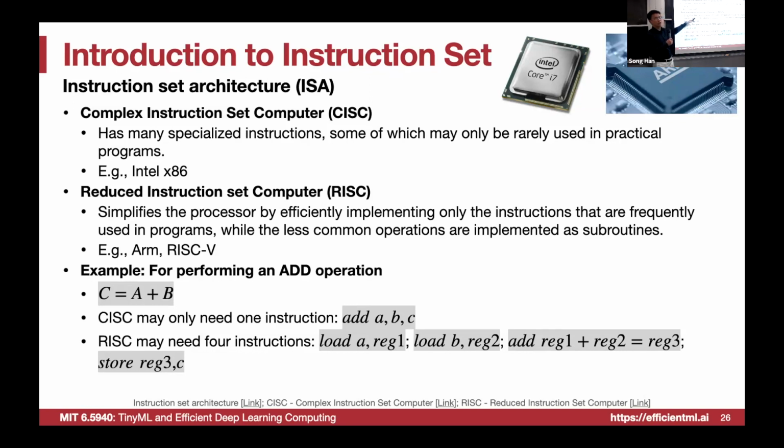Well, RISC is usually applied to low power processors. It's usually smaller instructions, much shorter, much more regular. It can do less work in each instruction. For the same program, we have to use more instructions here, but each instruction is more lightweight.